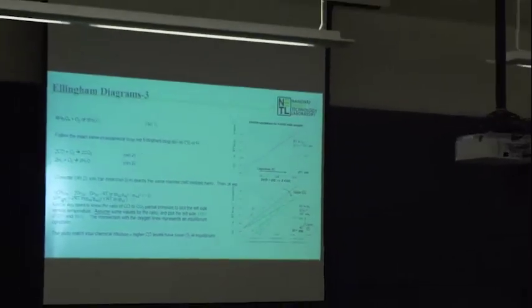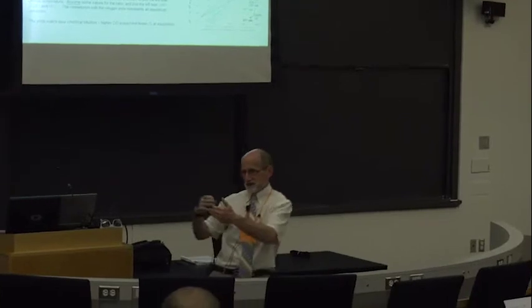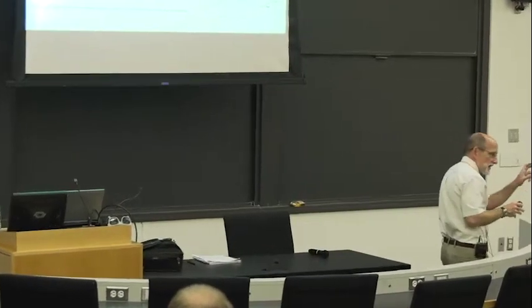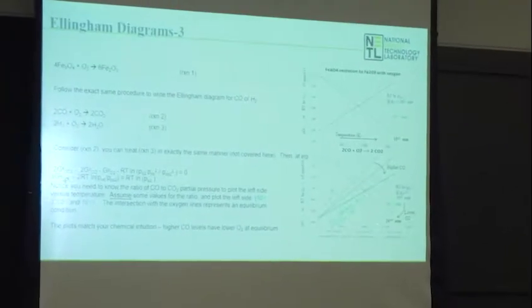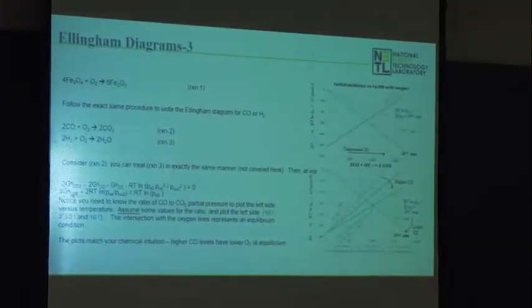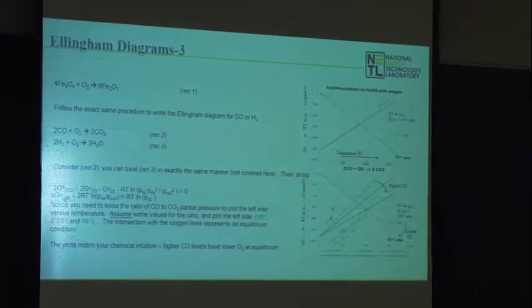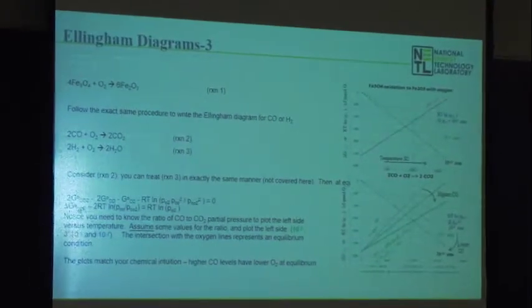It's different in a flowing system than a closed system. If you put it all in a box, you have it establish the CO2 level based on how much fuel is present. If you put it in a flowing system, you actually have a knob you can turn to control that ratio. But my point is, you establish the level of CO to CO2 in that system, and that will set a value at equilibrium of the partial pressure of oxygen, which is what we needed to figure out what happened to the metal, right? I'm looking for that partial pressure of oxygen.